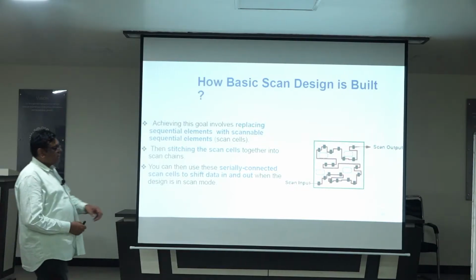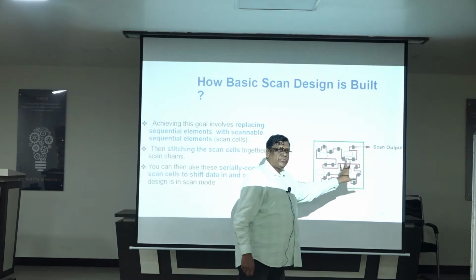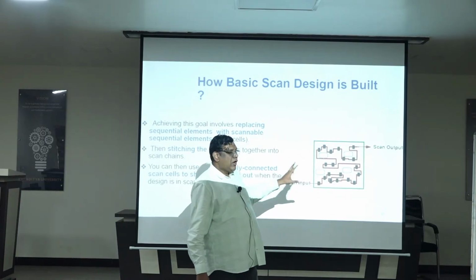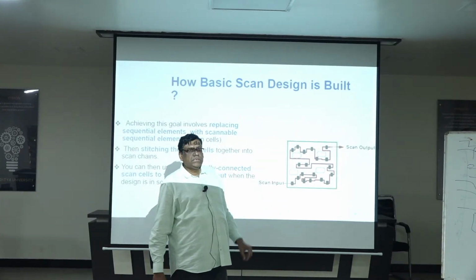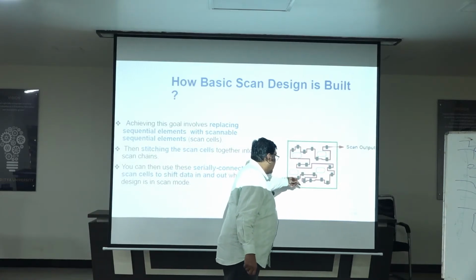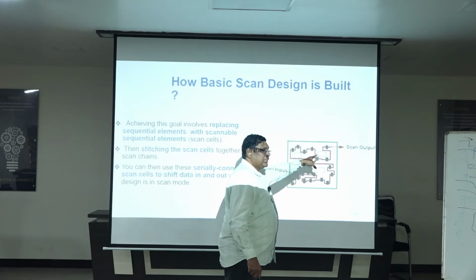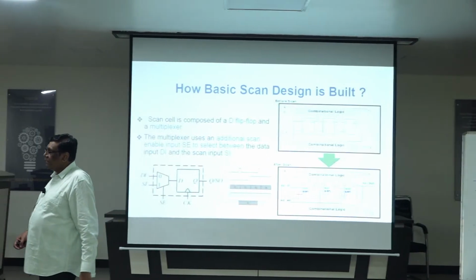Yeah, you can see here the same concept. Scan in, these are all the D flip-flops. All D flip-flops are connected in shift register fashion. So data we will send to this. Data will be captured onto all the flops. Then I will show you on the next slide what will happen.